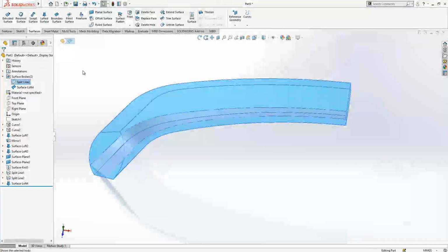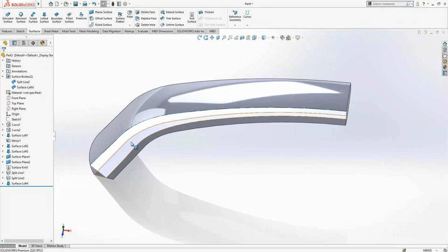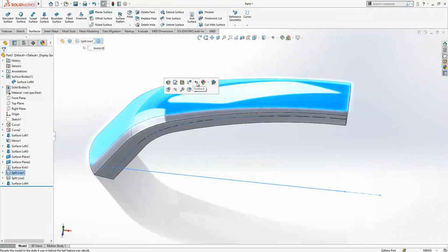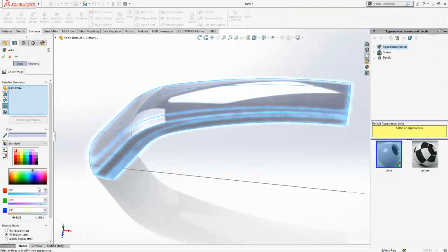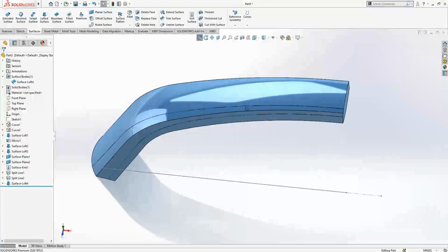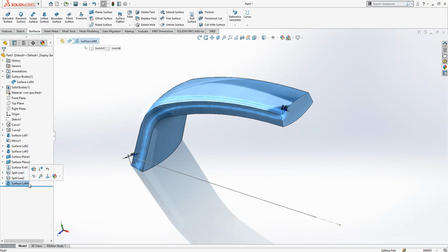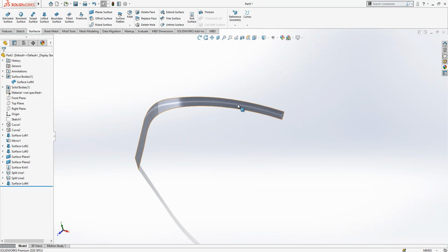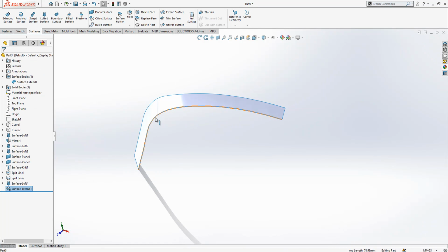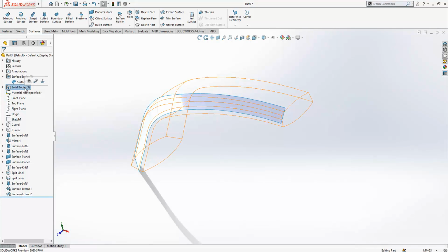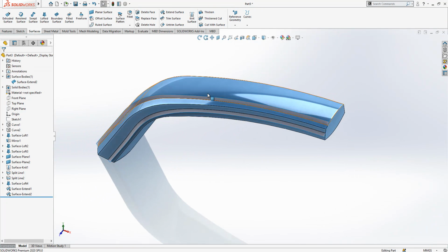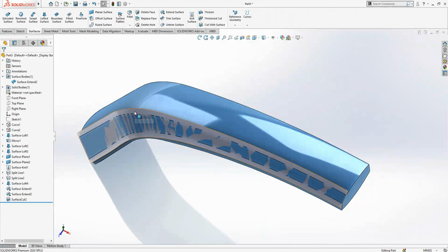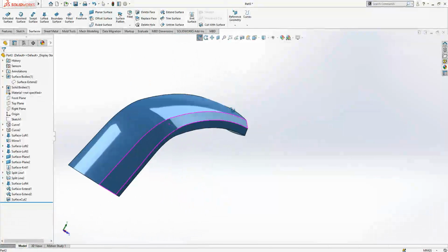And model here, we can color model. Seems we didn't complete create solid, it is still on the surface bodies. This is body, let's give a color to it, something like this. Pretty much done. We have here a surface loft and we're gonna make with that a surface cut. This is a frequent problem, then you need to extend a bit the surface. Extend surface. Good. Guys, if you were to pay for a course, even you wouldn't get this level of modeling detail. I really make here real life modeling for you. Yeah, that's really nice.